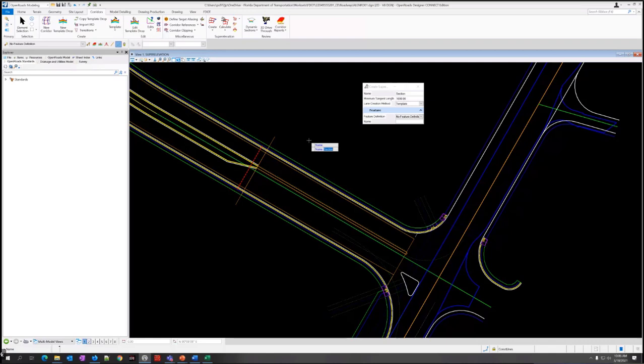All right, so the name, I'm going to call it SR61. And then I'm going to select, it asks me to locate the corridor or alignment. This is where I'm going to select the corridor handle down here, not the alignment. Oh, one caveat here. There's an option for feature definition. So you want to select that super elevation manually because it doesn't actually prompt you for the feature definition, I believe. So it's better to just go ahead and set it here in the dialog. Just set that feature definition.